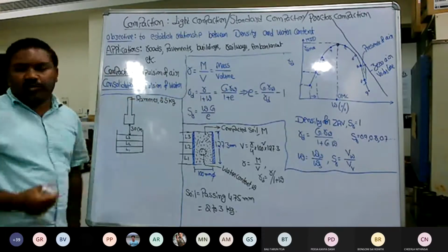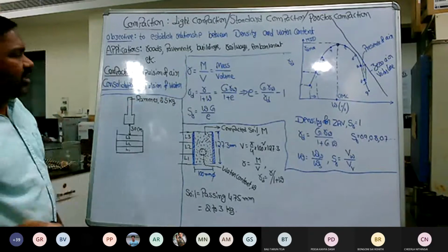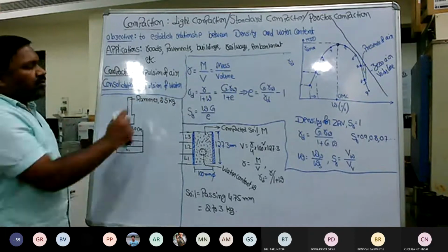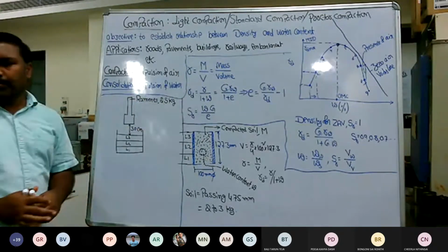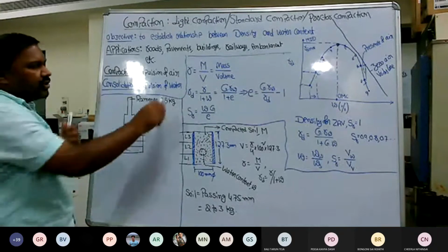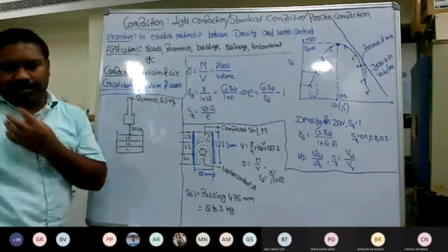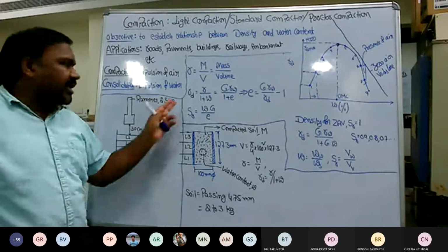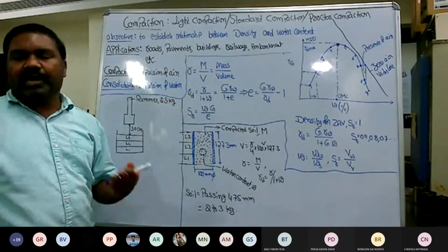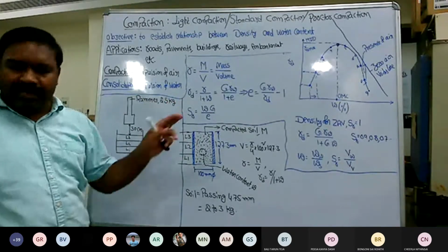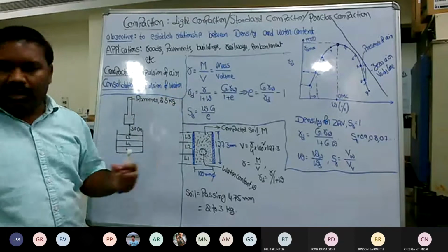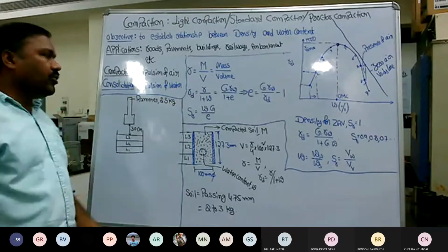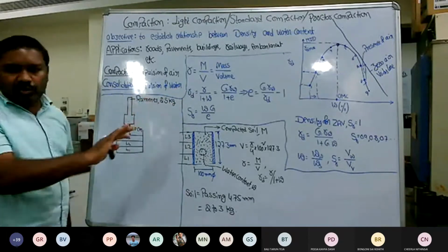Removal of the air is a quick process. It can be done in a fraction of minutes. While removal of the water takes an immense amount of time. It is months, rather years, of a process. If you want to remove the water from any soil, especially clay, you may need 1 year, 2 years, 5 years, 20 years, 30 years, depending upon the soil type. Therefore, dealing with consolidation is altogether different.